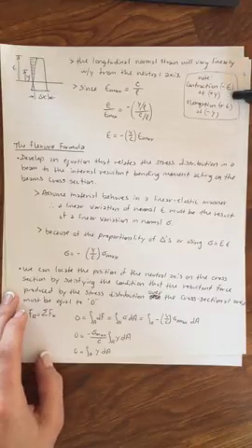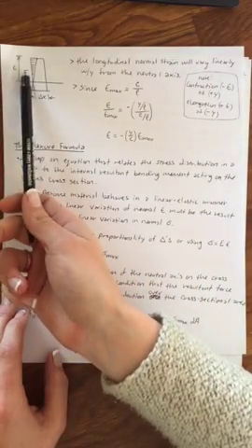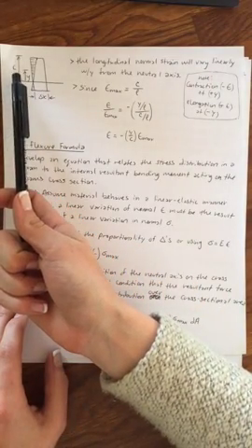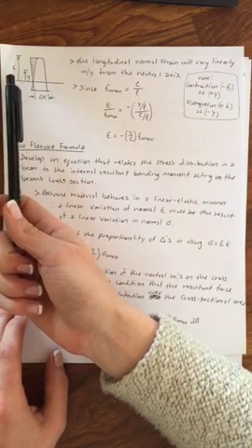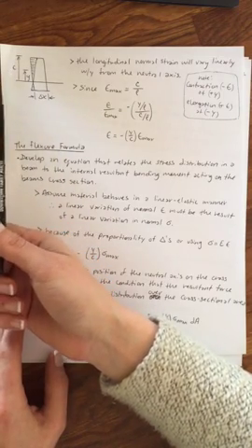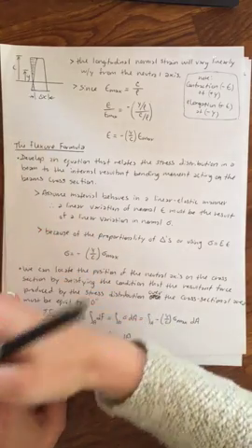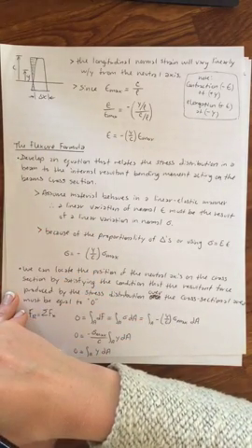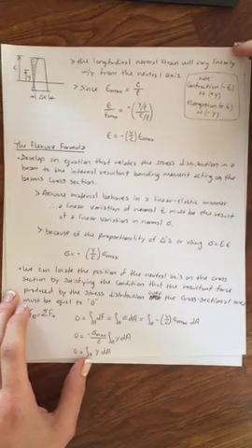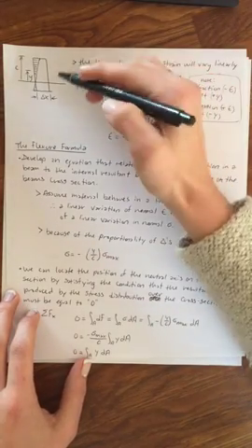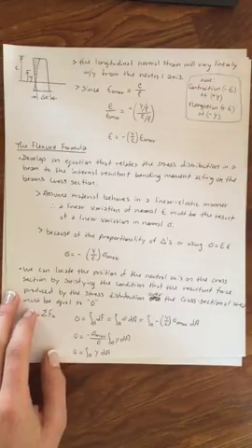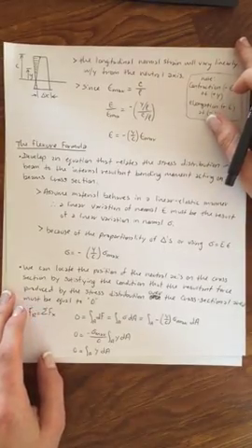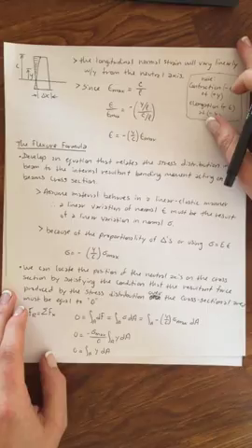And this is just a note writing out what I was saying earlier, so you can always keep in mind that when there's a contraction, which always occurs in the positive y, that's negative strain, and an elongation, which occurs in the negative y, is a positive strain. So that's our standard there. And this is just a little diagram more explaining some of the variables I'm using. So this is how we describe the strain on a member in bending.